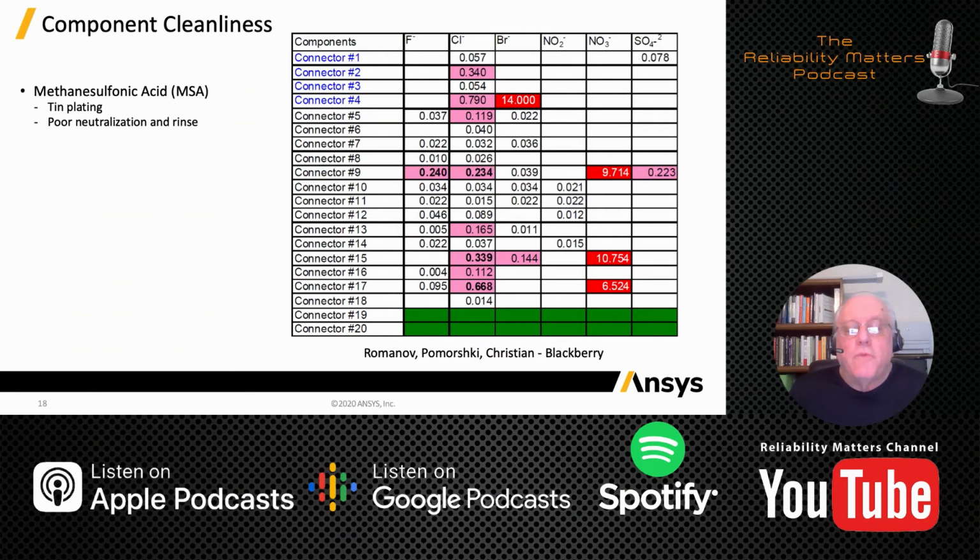What they've showed conclusively was that it's not enough to have the temperature ramp on your reflow get to that high temperature. So if you have components, QFN components as an example, ferrite filter components as another, where the outgassing and temperature processing does not reach into the interior of the components, the fluxes on the outside edges tend to seal off the evaporation from the inside.